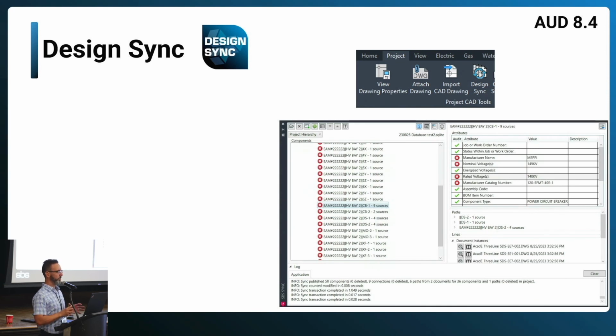So the main thrust of this is to be used in a scenario where you have a substation planning and control drawing set, and you have a physical drawing, and you can publish all that information together, and this tool will help analyze and make sure that all the data is consistent, right? That all of the ratings are the same, that all of the tags and identifiers match between those.